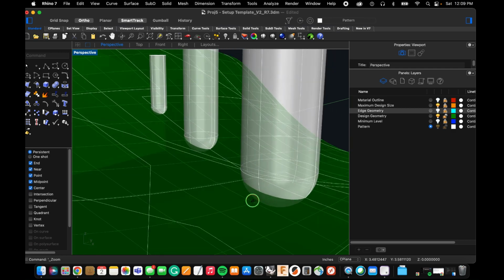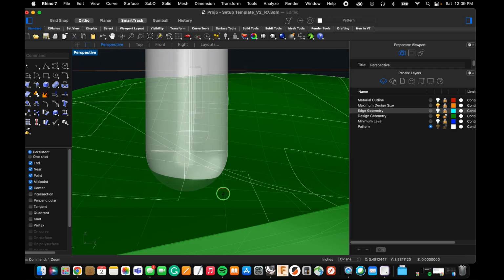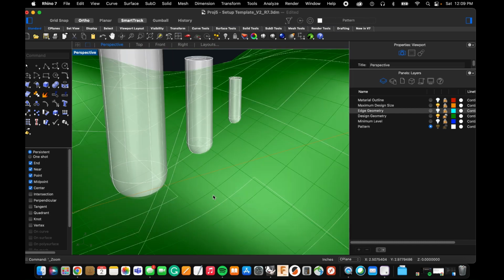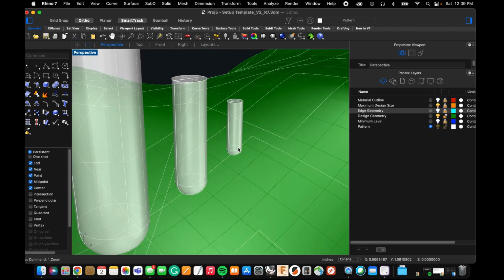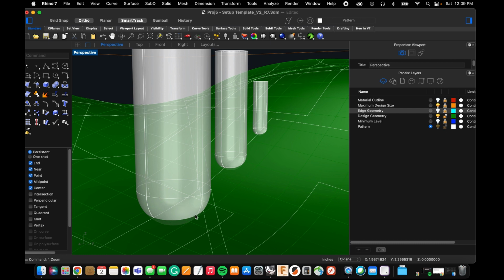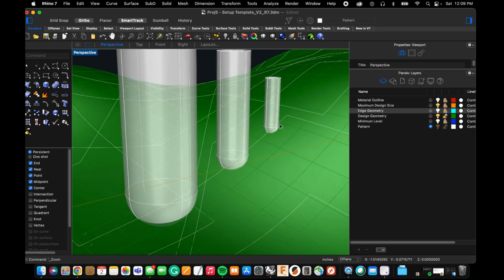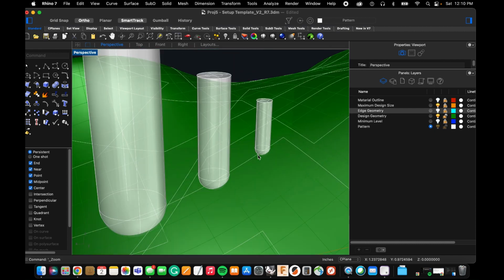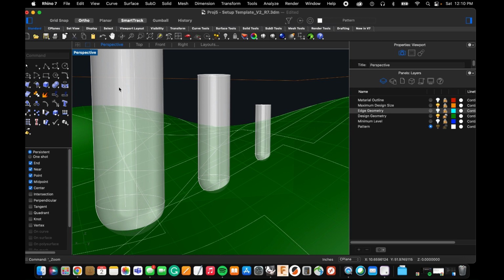Okay, so the bigger the tool, the deeper it goes, and then the wider the trough that gets created, with less detail that we would probably tend to get. The smaller the tool, the less deep it goes, but the narrower the width of the trough that gets created, and that's great for detail stuff. Okay, now this will take longer to machine than this will.